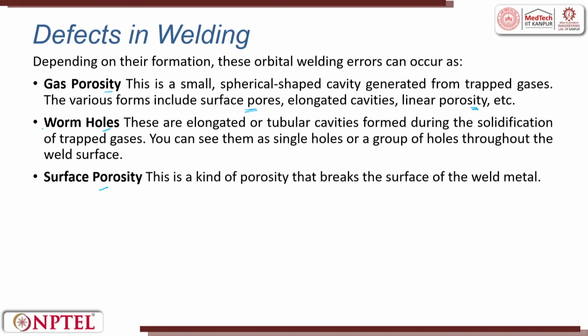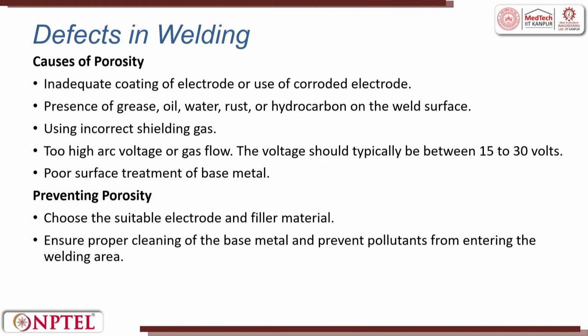When we talk about wormholes, they are elongated and tubular cavities. Gas porosity is spherical, worm is tubular. Surface porosity is everything that comes to the surface and breaks the surface of the weld. Again, the prevention can be suitable electrode, filler, and cleaning.